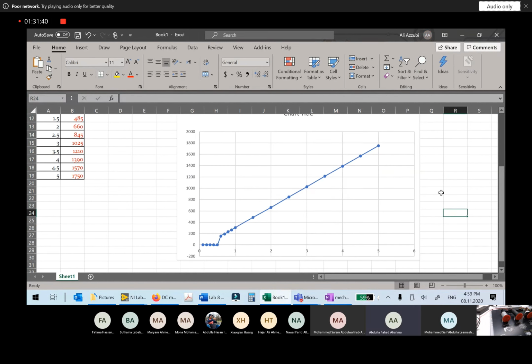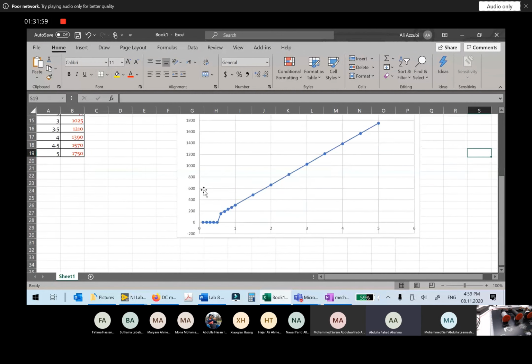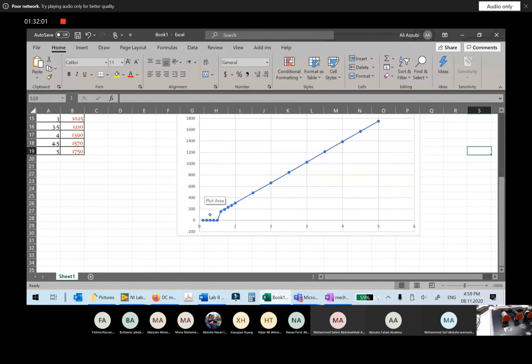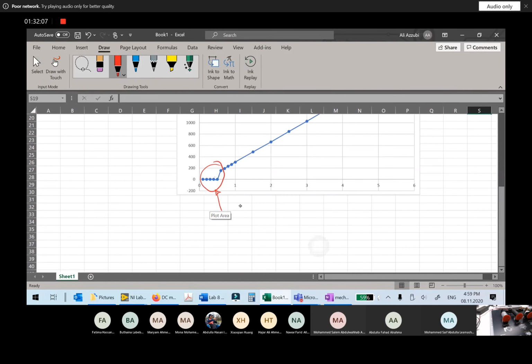At first, no, then it's linear. Why? You're right, at the beginning until 0.5 something, you have 0 RPM, but then suddenly you have some linear curve. Now we know this region here is what you call dead band. This is because of friction.